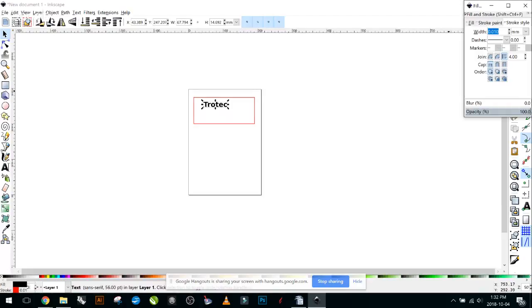Okay. So if it's not working for you guys, just make sure you press enter. I think that's where I was having some problems here. You can't just click away, it won't enable it. So make sure you're pressing enter for your stroke here. So again, for Inkscape, for the laser to register this, you're going to want to make sure that it's RGB red and that you do have a stroke enabled. If you don't want a cut line, make sure that your strokes are 0, or else the laser is going to recognize it as a cut line.